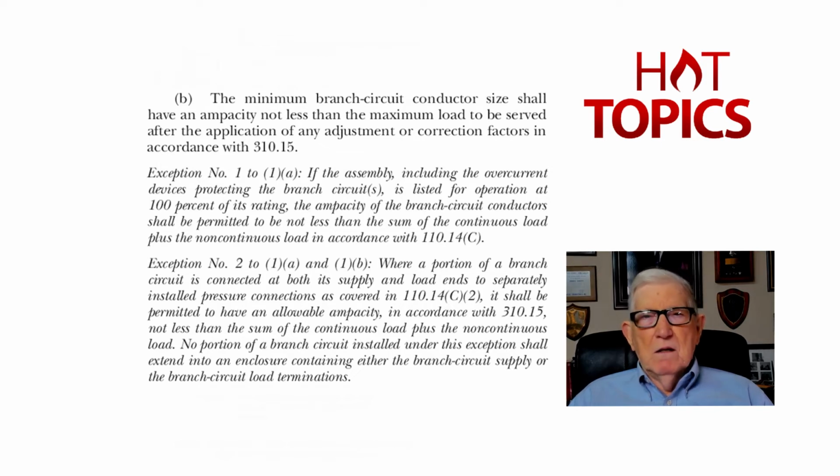But an overload is anything that exceeds basically the 125% rule that we figure our overload protection, 125% of the load. Then a circuit breaker would have overload protection if we could design it within that value after we do the calculation.